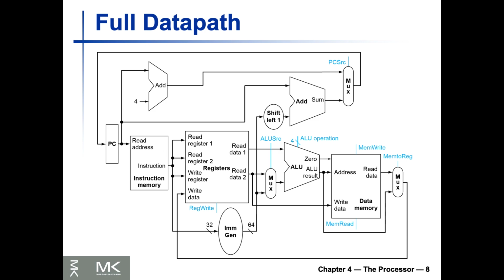As you see, this data path that we just designed by adding those three different smaller modules together can execute basic instructions. What it can do is load, store, register operations using the register file, ALU operations, and also branch. It is able to do all of those in one cycle. So branch in one cycle, store in one cycle, and so on and so forth.